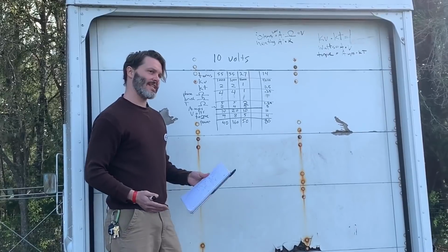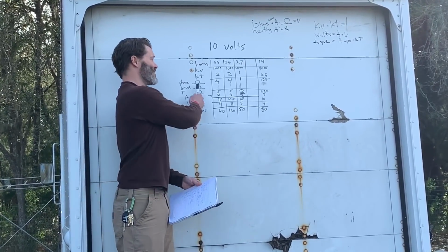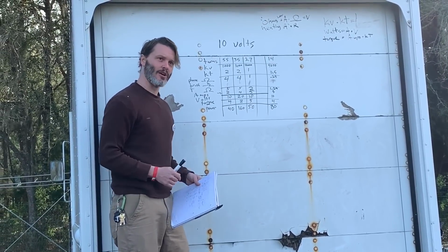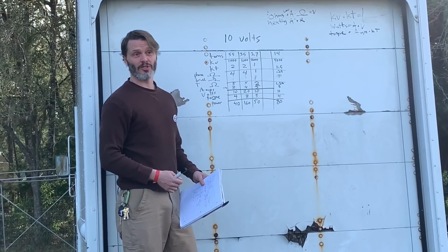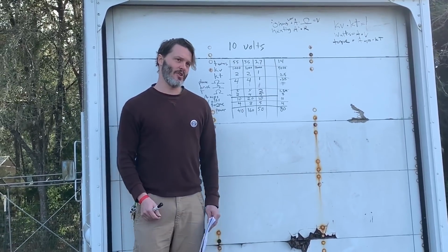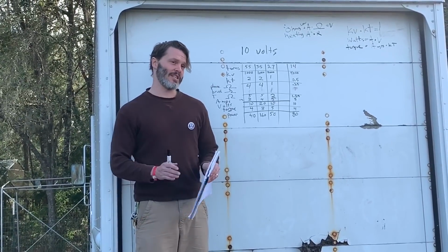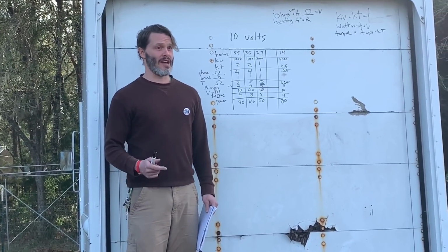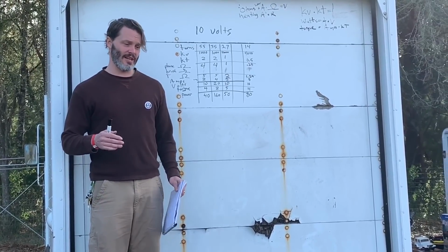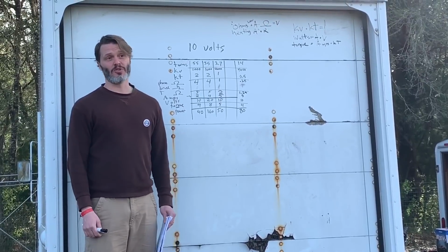And more or less, that's how motors work. Whenever you smooth out the startup of a motor, your phase resistance ends up going up just a little bit, and so your amp efficiency goes down a little bit. It won't produce as much stall torque. And that's a constant, although it's not guaranteed. There are ways to make really smooth motors that are also torque dense, but when you're trying to compare apples to apples, that is the trade-off. If you have a motor that's a little bit smoother, it's not going to produce as much torque, it's not going to have that inrush of current so much, and it's going to be a little bit easier to control.